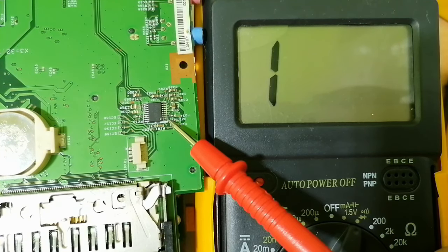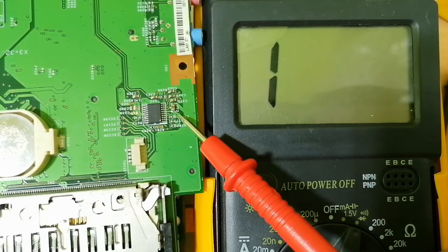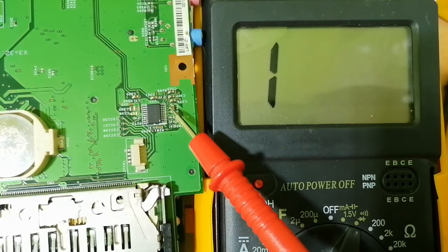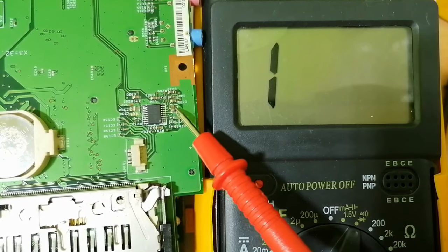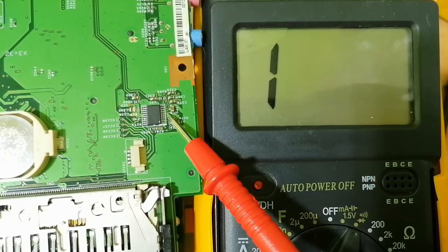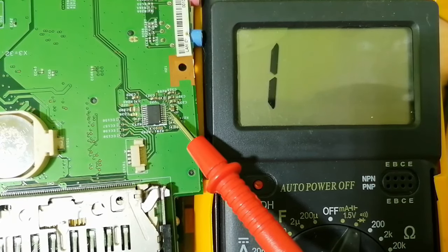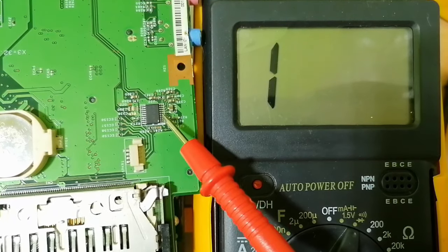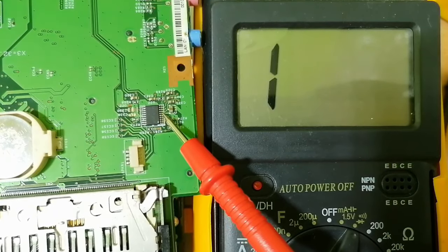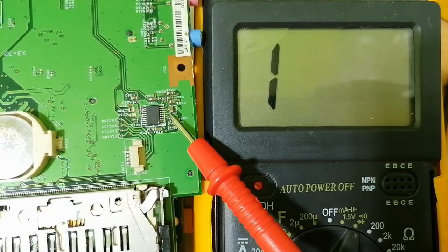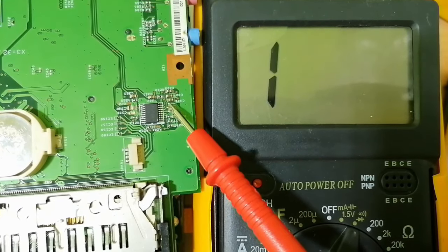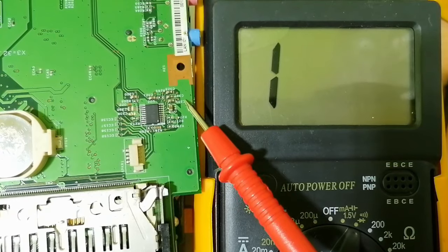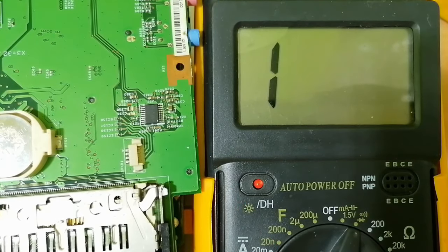Power capacitors are the capacitors that feed the IC with the voltage, like this one, for example. Do you see this one? Here we have a bolded line, which means the input for this IC is from here. So this pin of the IC is connected to this capacitor. As you can see, we have the path here, and the other terminal of the capacitor is connected to ground. We can even check using the multimeter.